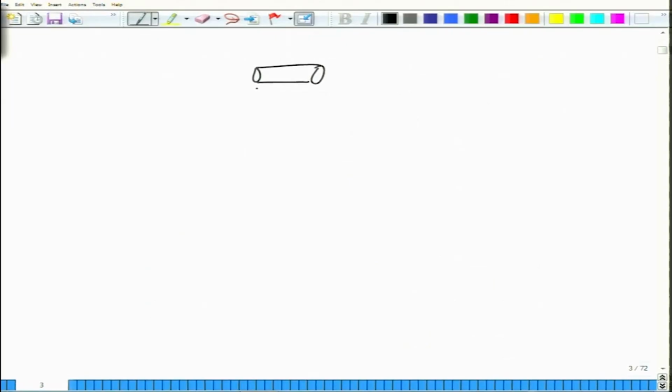While the forward pump drops down, is it possible for us to use a secondary pump in the backward direction, while the forward pump starts off very strong and then eventually falls off? What if we had another pump in the backward direction, which would start off strongly here and then go down as it goes, eventually creating an overall gain? It is possible for us to do so. This is called a co-propagating pump, and this of course is called a counter propagating pump.